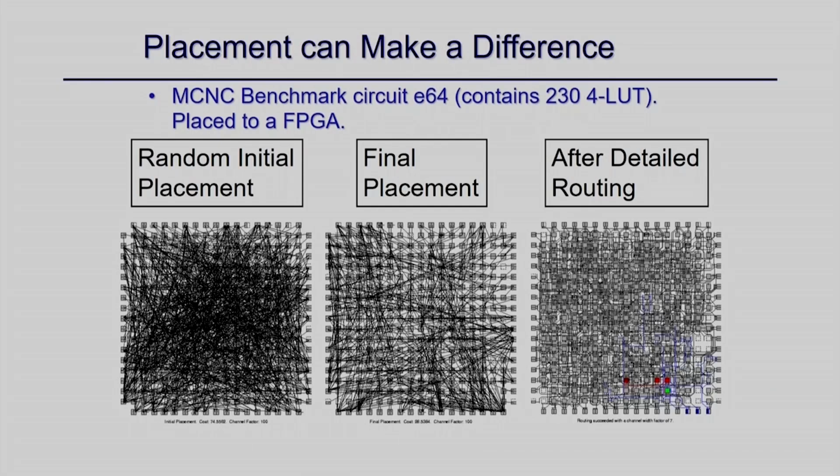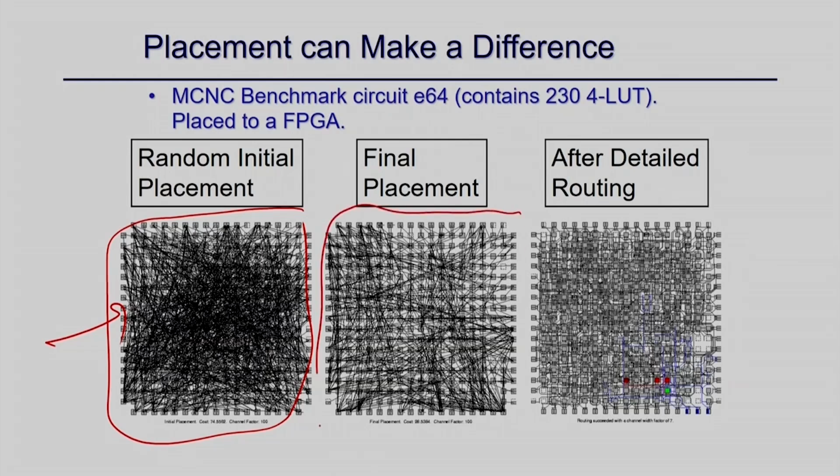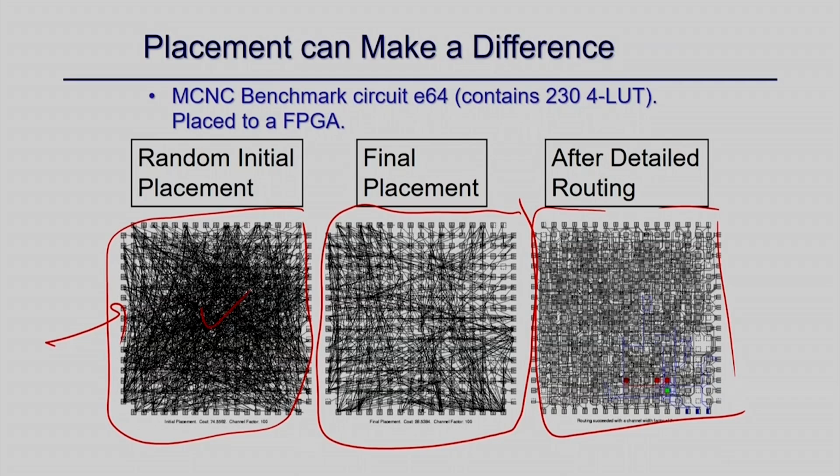So, you can see there is some random initial placement generated by floor plan. Effectively, the placement looks like this, right. This is just a snapshot of the layout, but you can make some modification. You see the wire length becomes very less here, right. So, this is very sparse compared to this dense placement, and this is after final routing. So, you can see that you can actually make a lot of interconnections less just by moving your blocks during placement. So, the placement has a huge impact on the final route interconnection cost, right.